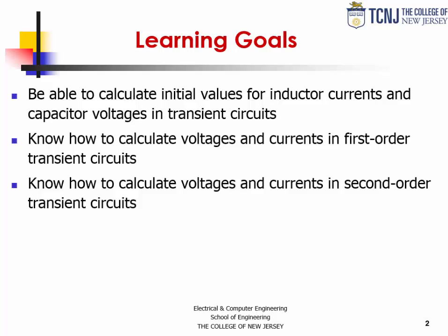The circuits that have only one energy storage component, such as a capacitor or an inductor and a resistor, those will be first order circuits as given by the differential equation that describe them. And the ones that have all three components, the LRC circuits, will be second order circuits according to the differential equation that will describe such circuits, both the series and the parallel circuits.